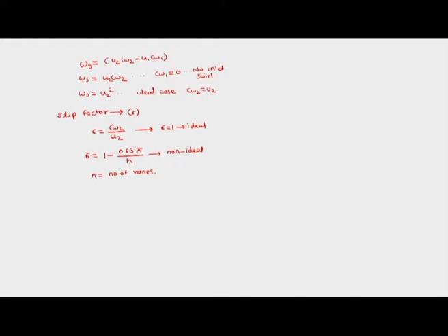Okay, so the inertia effect will be reduced, and it should be pointed out here that this effect of inertia leads to sigma, which is the slip factor, but there is no role of frictional loss here. Sigma is due to inertia. So we would have Ws, which is stage work, equal to U2 CW2, which is equal to sigma U2 square. This is the stage work.